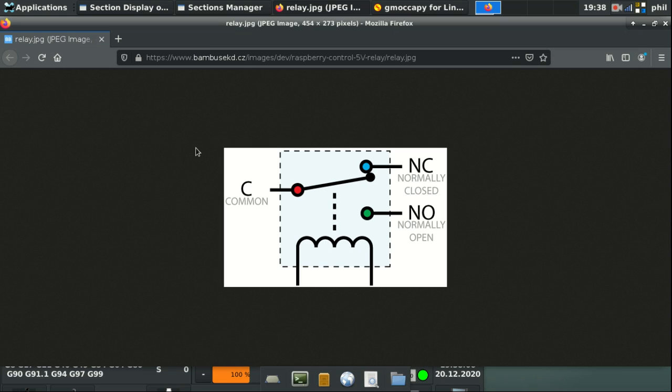On my CNC router, the tool setter and my spindle probe are tied to the same input using a relay. And again, the downside to that relay, and somebody had asked me last week, well, what do you do when that relay fails? Well, I'm going to nip that in the bud and create ladder logic and just use two physical inputs on my breakout board instead of using a single input and dividing that signal with a mechanical relay. So that's what we're going to do tonight.